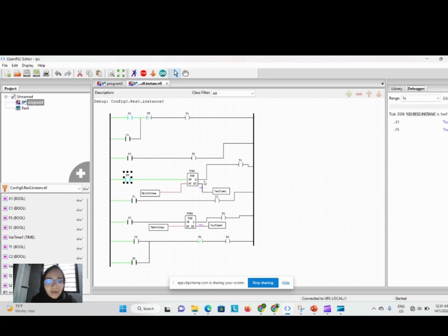So at the end of 120 seconds, Relay C2 will energize, that means it will activate our timer T2 for 20 seconds, and our solenoid S2 also will be energized to drain the tank. So after 90 seconds, the timer will break and solenoid S2 will be de-energized.